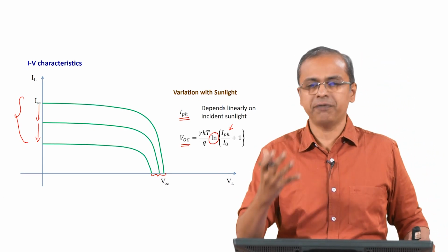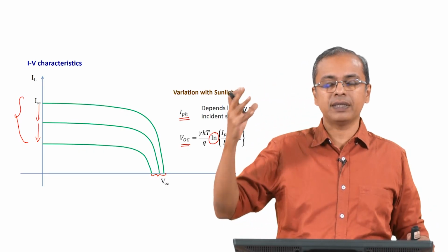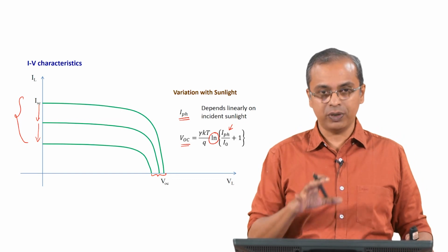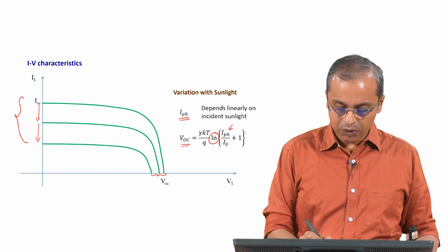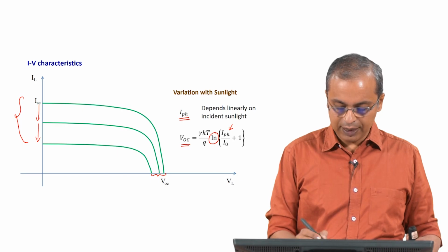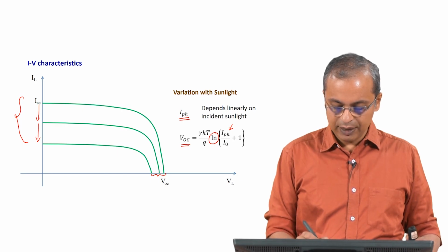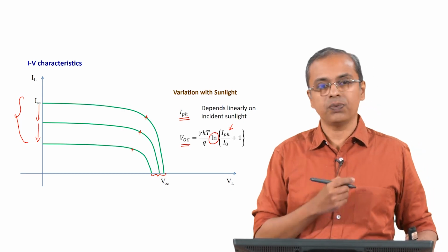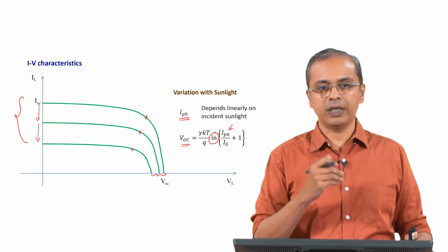So, a solar cell behaves differently from what we intuitively think it might do. Or at least we may be unaware that it is doing all these things; this is what it is doing. So, again you have to look at the fact that there are peak power points. You will have some peak power point here corresponding to this, some other peak power point here, some other peak power point here. So, you have to keep track of this peak power point and accordingly use it.